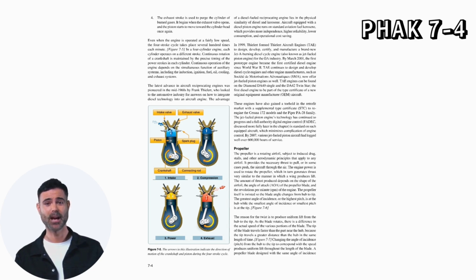TAE continues to design and develop diesel cycle engines, and other engine manufacturers, such as Société de Motorisation Aéronautique (SMA), now offer jet-fueled piston engines as well. TAE engines can be found on the Diamond DA40 single and the DA42 Twin Star, the first diesel engine to be part of the type certificate of a new original equipment manufacturer (OEM) aircraft. These engines have also gained a toehold in the retrofit market with a supplemental type certificate (STC) to re-engine the Cessna 172 models and the Piper PA-28 family.